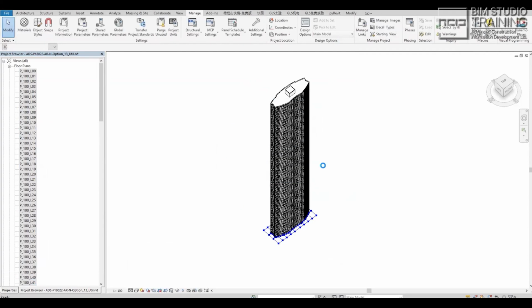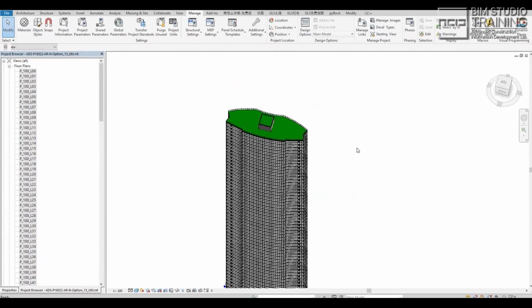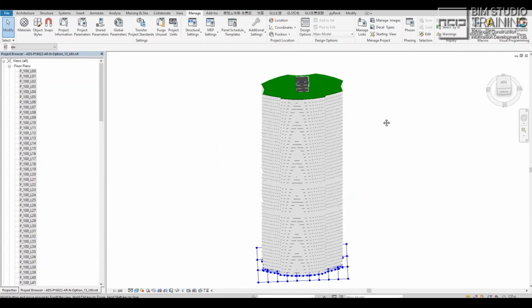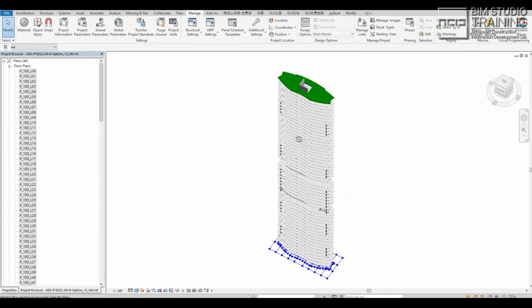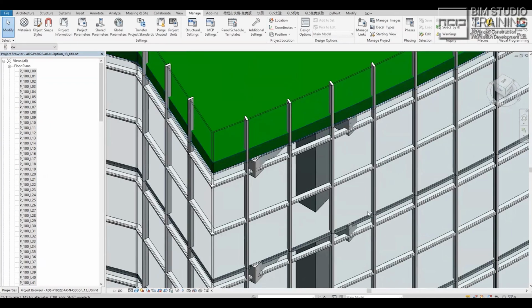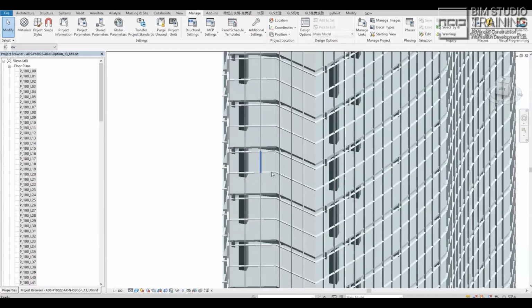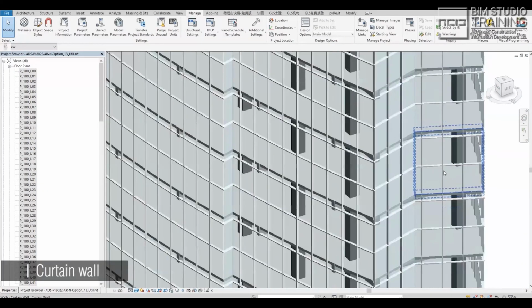So I'm using Revit. All you see here is automatically generated. It's not manually produced. What I did as a designer, I just give it a shape. With the shape, it calculates the area. The total area divided by the floor area, you calculate the number of floors. So for every floor, what's the floor to floor ratio, and what's the floor to floor height?